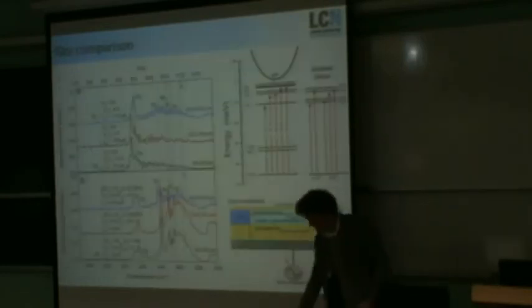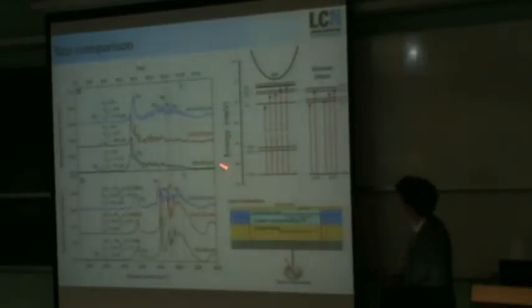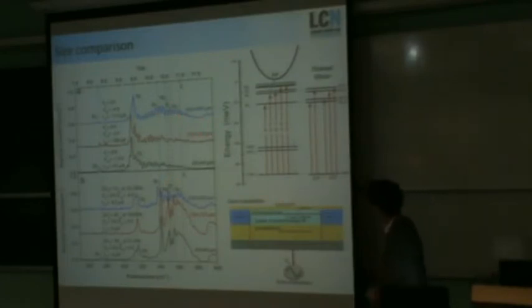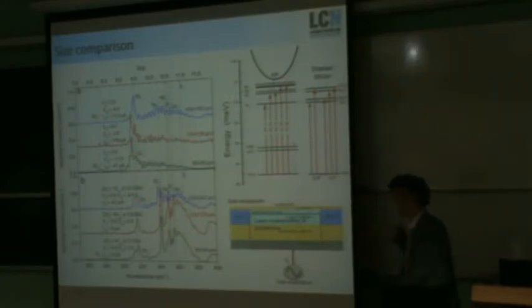So again, by comparing this between all the different device sizes, you can see you get a relatively similar result when you just do a regular FTIR spectrum. There's a bit of perturbation because of the stress and strain in the actual device layer in some of the smaller devices. And I think also there's a bit of problems with the oxide quality, being a very poor quality oxide. But what's interesting is with all these samples, if you do a gate modulation detection method, you can actually clean up the signal quite nicely and see a lot of the much higher lying states.